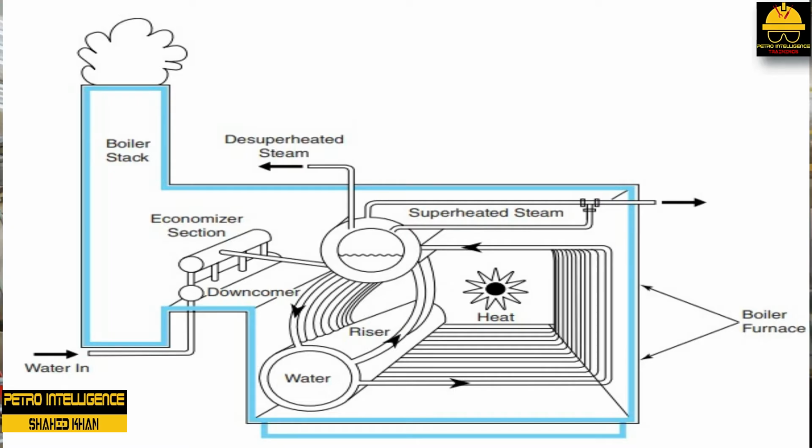exit the boiler. As heat is applied to the boiler firebox, water flows from the upper drum through downcomers into the lower drum. Tubes, called risers, cause water and steam to flow into the upper drum because of density differences. Boiler water circulation operates under the principle of differential density. When a fluid is heated, it expands and becomes less dense.